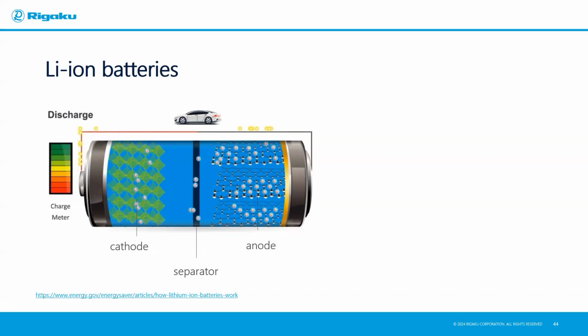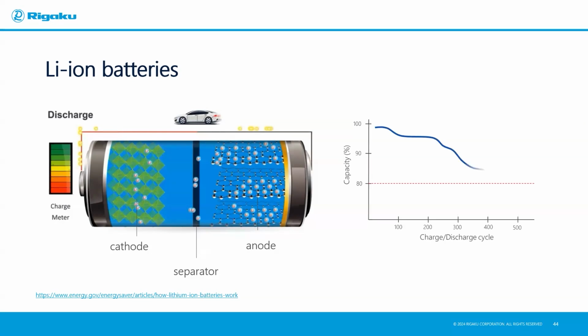Instead, you usually end up with some lithium accumulation, and that accumulation can form stress, and it can form cracks, it can form gas inside, and with more charge and discharge cycles, the battery capacity is reduced until the battery reaches its end of life. And generally that's defined by the industry at about 80% capacity.